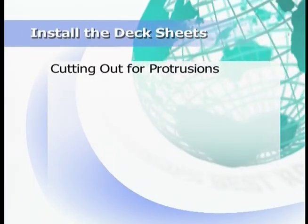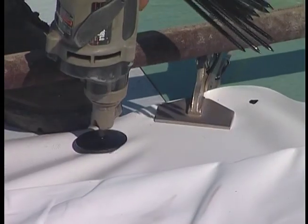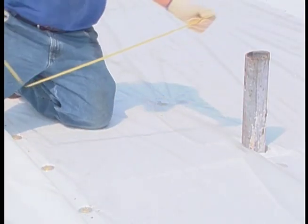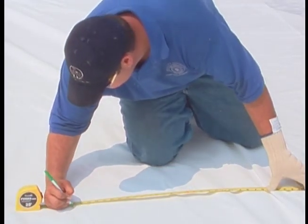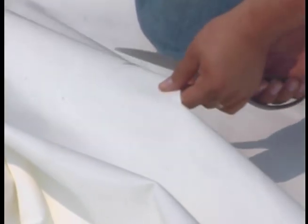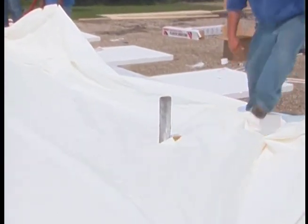Now, let's examine how to cut out for protrusions in the roof deck. First, fasten the tab closest to the protrusion. Measure from the base of the protrusion to the edge of the factory weld on the fastening tab. Measure from the weld the same distance back on the uninstalled membrane and mark the distance. Now make a cut in the shape of an X for the protrusion. You must use caution to be sure only the top layer of the membrane is cut. This will allow the protrusion to push through the Duro-Last membrane when the next fastening tab is pulled out.